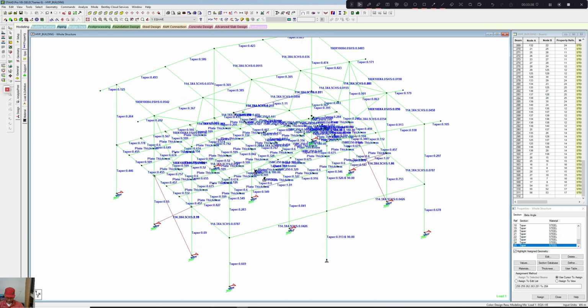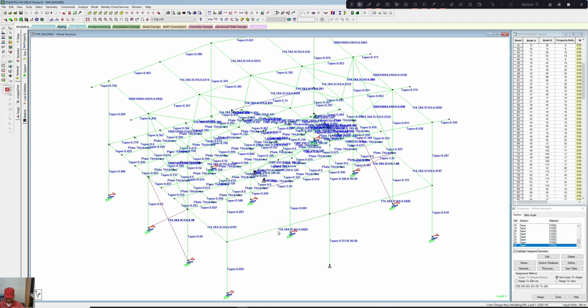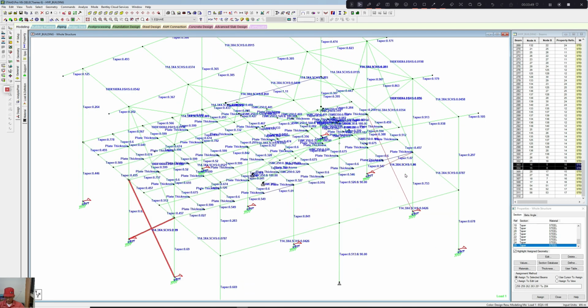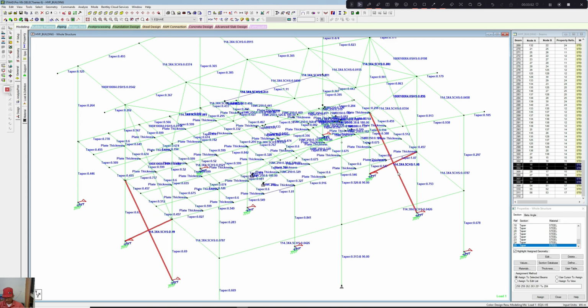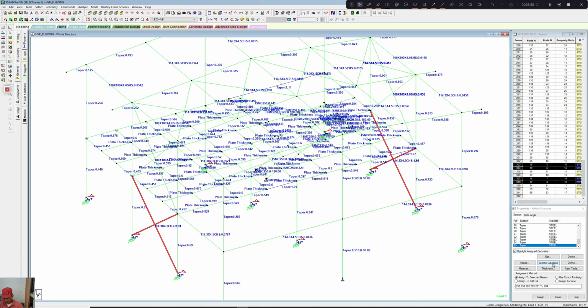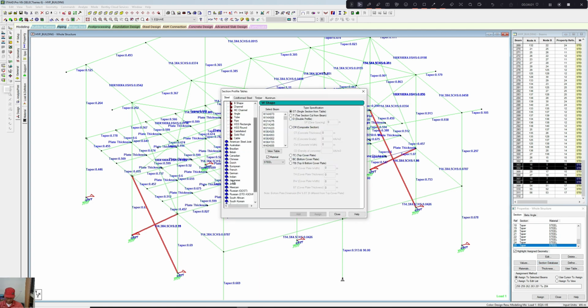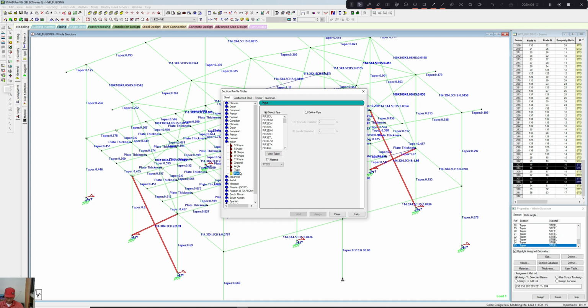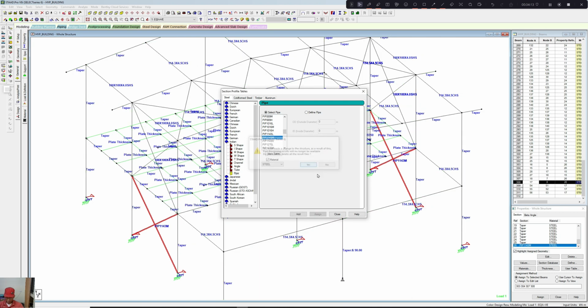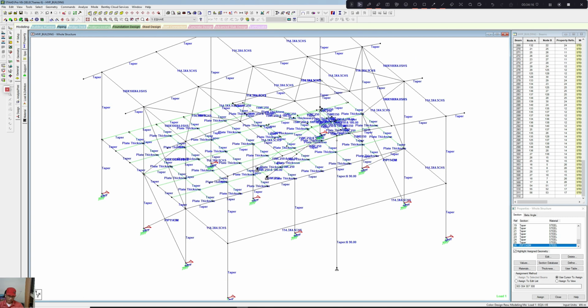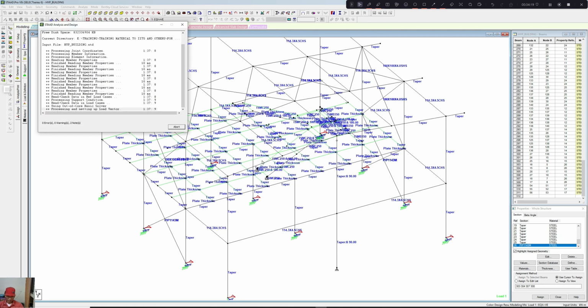So let us go to this. Now our 114 mm beam is okay, but these bracing members are not okay. So let us give a higher section from the database. Go to Indian pipe, 100 mm nominal bore is 114 mm outside diameter, medium, assign. Run analysis.